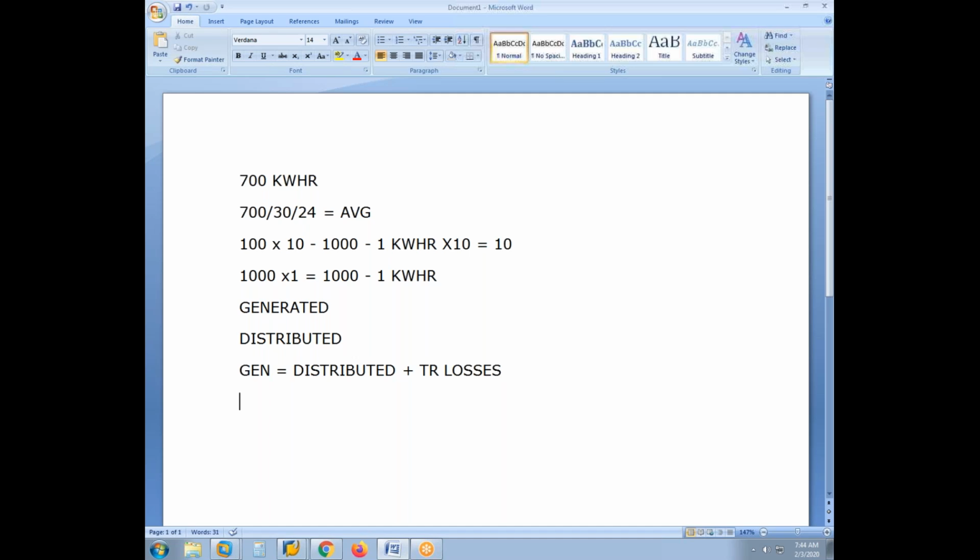Rather, the industry requirement was always, why not do the settlement once in a day or every hourly settlement. Now many countries are doing settlement every hour. That means if you have the data of the consumption happening every hour in various areas, we can also do the settlement. But there's no way this could have been done with the regular meter. That's how there was always a requirement to develop a kind of meter which will keep on recording the consumption for smaller intervals of time. And that's how the interval meter came into existence. It is also called a smart meter.